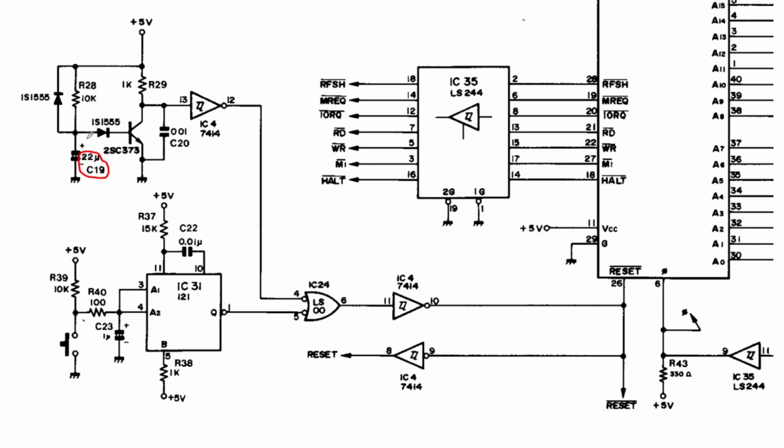When it's discharged, there is no base potential here through this diode on the base of this transistor, the 2SC373. Therefore, the transistor is open, and therefore the 5-volt potential goes into the input of the inverter. So this will be a 1 because the inverter inverts. This becomes a 0, and the computer is in a reset state when you turn it on.